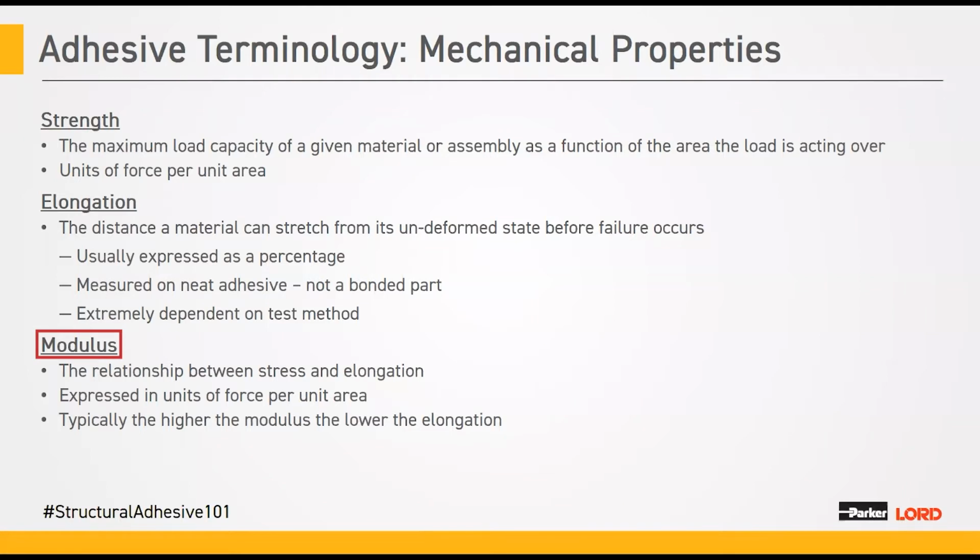Modulus is often listed and used from an engineering standpoint where customers can begin to design a part. It's simply the relationship of stress versus the elongation. It's expressed in a force per unit area. And typically the higher the modulus, the lower the elongation.